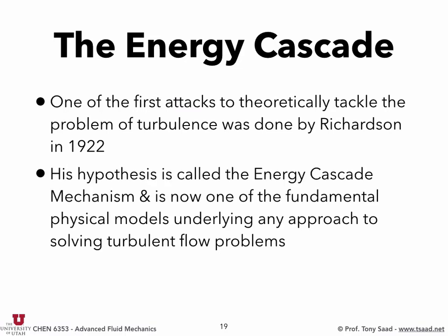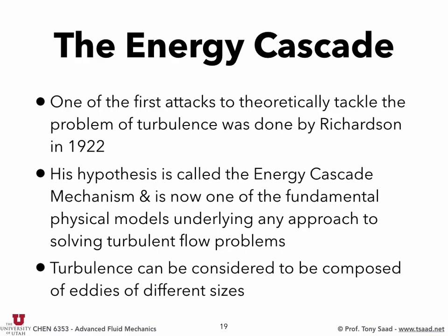and his hypothesis says that turbulence consists of eddies, and we know what an eddy is. It's just like a vortex, it's a region of the flow that is rotating. And as we saw from the simulations earlier, you have eddies that are the size of the domain, eddies that are half of that, and half of that, and half of that, all the way down to the molecular scale, okay? And big eddies can contain small eddies, and smaller eddies can contain smaller eddies, and so on.